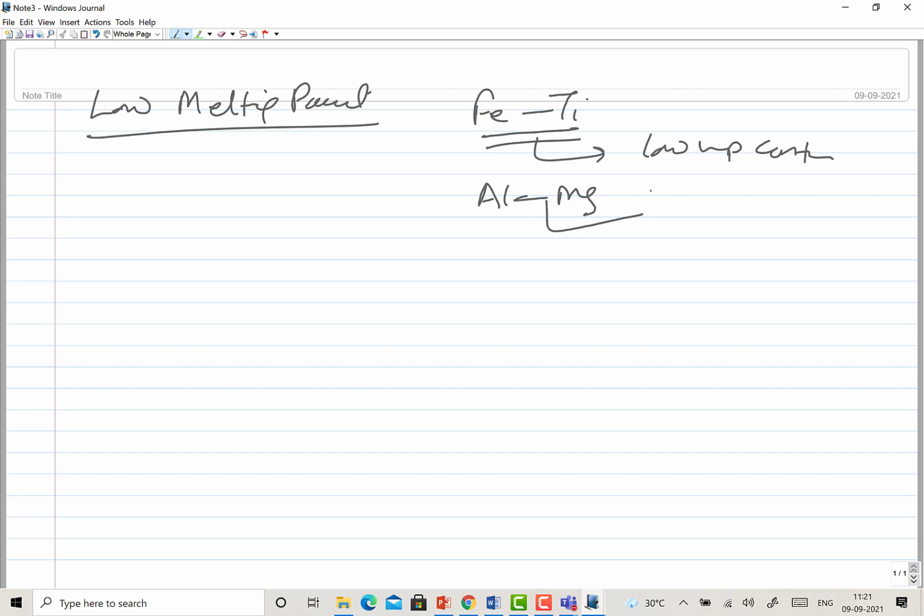These also lead to the formation of low melting point phases. And whenever these low melting point eutectic constituents are found, they are mostly hard and brittle, and if present at the interface, they will compromise the load carrying capability of the joint.